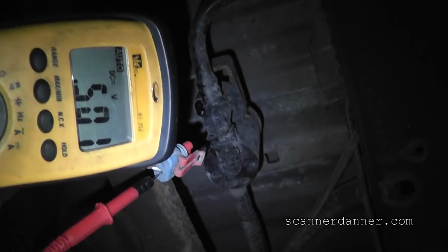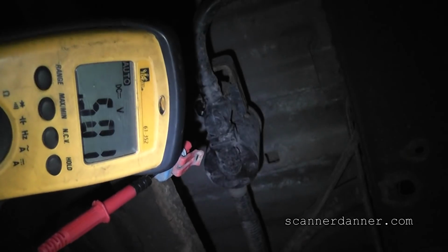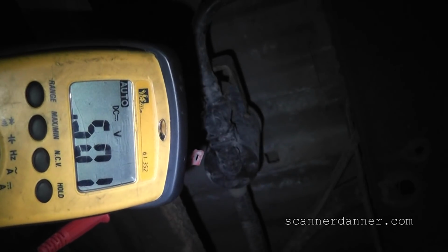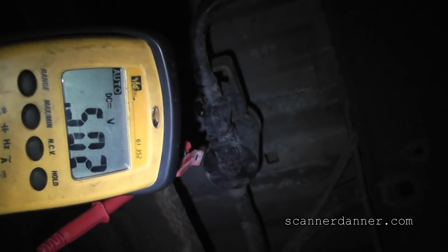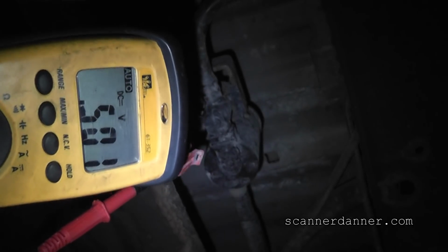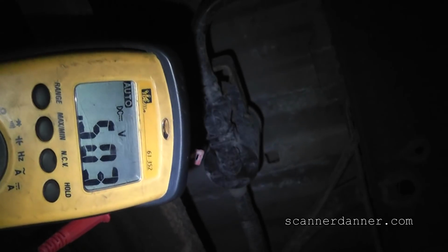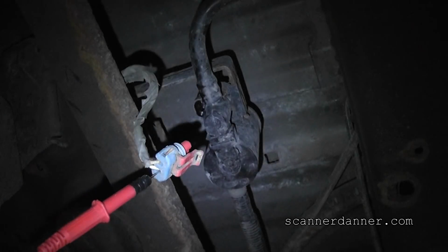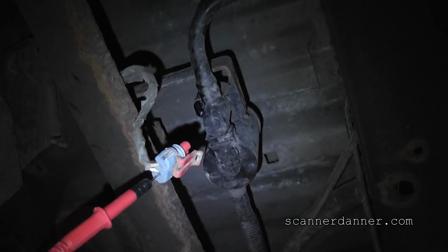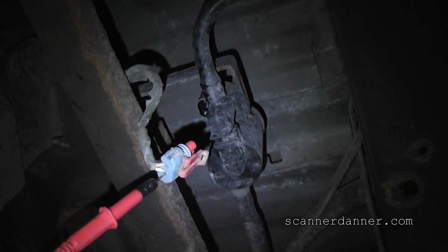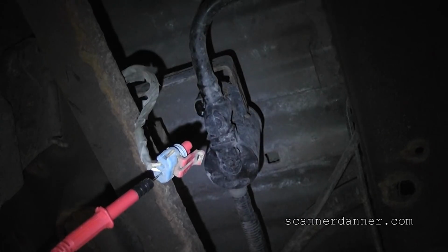Most likely it is. It could also be a bias voltage that's coming from the computer. In any case, what we know is that was not coming through the solenoid. That's just a trace voltage on the circuit. Whether it be a bias from the computer or picking up outside voltage is irrelevant. Open vent solenoid, no question about it. Our driver is good. Our control circuit is good.